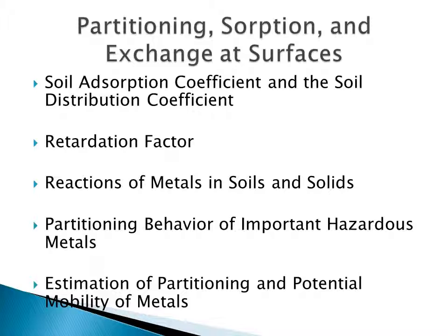Just as organic compounds are sorbed and retarded in soils, the rate of metals migration is usually slower than the rate of water movement due to bonding and partition processes on organic matter and the surfaces of other minerals. The partitioning of metals is highly complex and depends on a number of environmental and sorbent properties such as pH, cation exchange capacity, redox potential, iron oxide content, etc. Unlike the modeling of organic hazardous compounds, reliable compound-specific distribution coefficients have not been developed for metals partitioning.